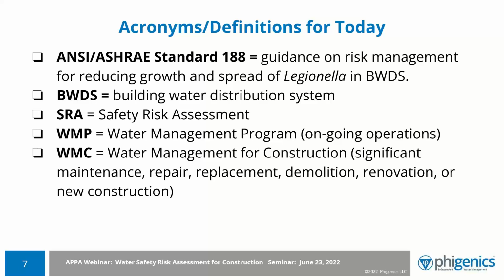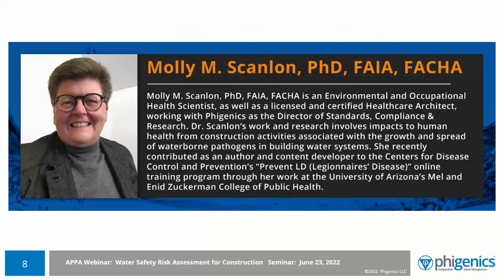So WMP is a water management program traditionally implemented based on Standard 188 for an ongoing or operational occupied facility, whereas water management for construction occurs for significant maintenance, repair, replacement, demolition, renovation, or new construction, and occurs in that time frame between either during construction or once construction is completed prior to occupancy of the facility.